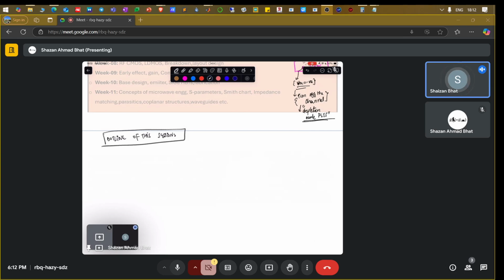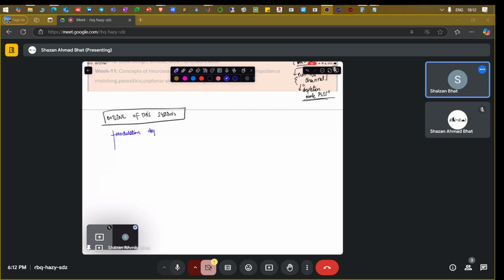First of all, we will cover what is called modulation doping, and we will cover HEMTs, which are III-V based high electron mobility transistors, but this will be particularly gallium arsenide, aluminum gallium arsenide based HEMTs. GaN, AlGaN based HEMTs will be talked about in the next lecture. Particularly, we will talk about scattering, and how it affects the mobility.